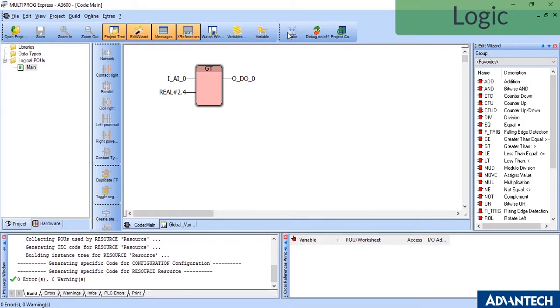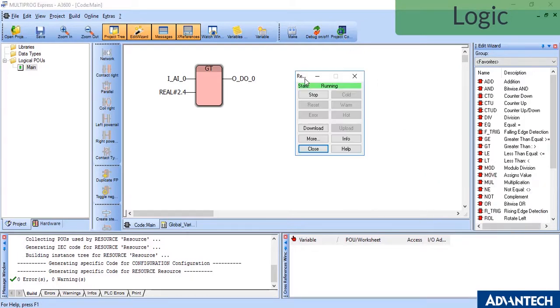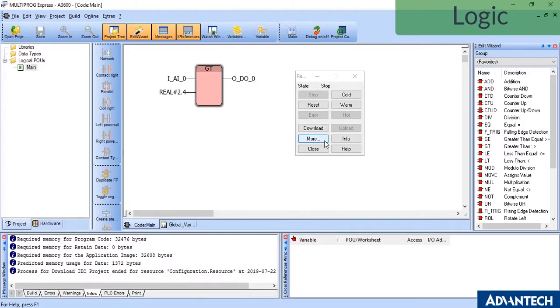And we had success, so I'll choose project control, very much like project download in the other. I will stop the existing runtime. And we'll download my new logic. And then basically hit go with the cold start function. So now it's running in a loop.